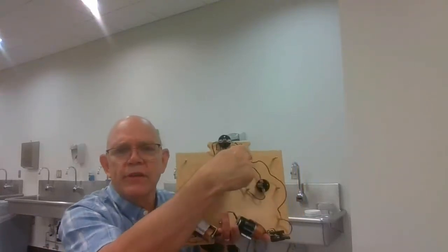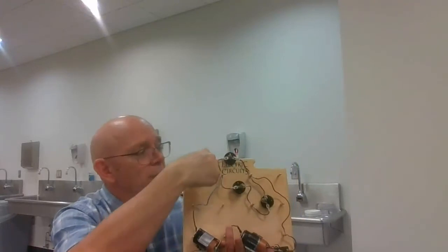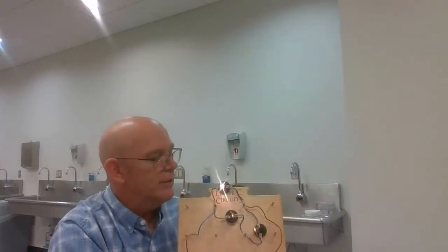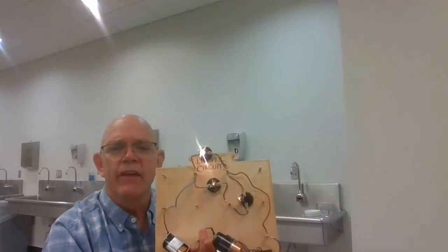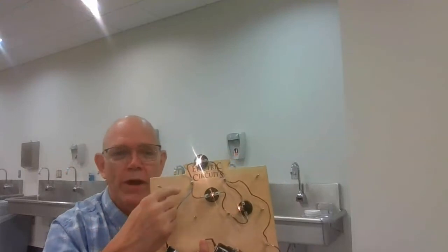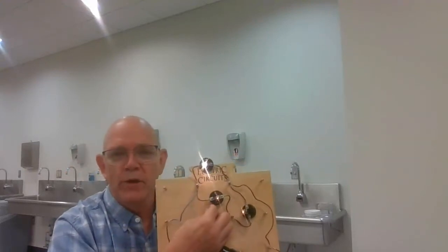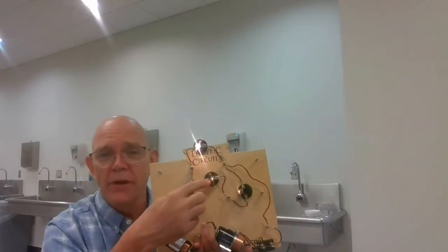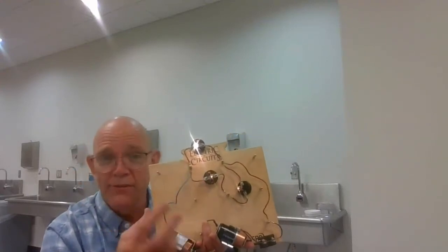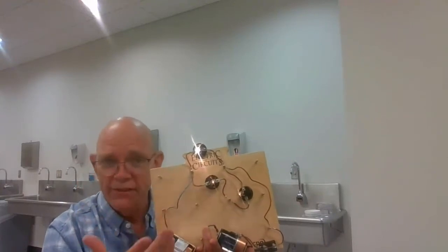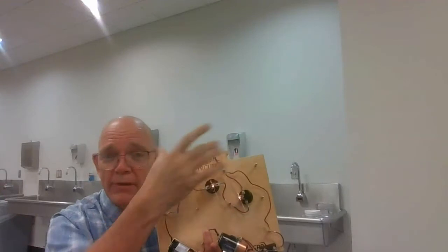Okay, so when the electricity comes over here, whoops, sorry. When the electricity comes over here, it can go on this top branch, which only has 1, or it can go on the bottom branch, which has 2. Now, let me see if I did that right. Okay, I did. All right, now notice something. Each branch, the top branch and the second branch down here, both get 3 volts of electricity. But on this branch, you have twice as much resistance because there's 2 bulbs on it, and they're in a row, so it's like a series. It's like a series circuit inside the parallel circuit.